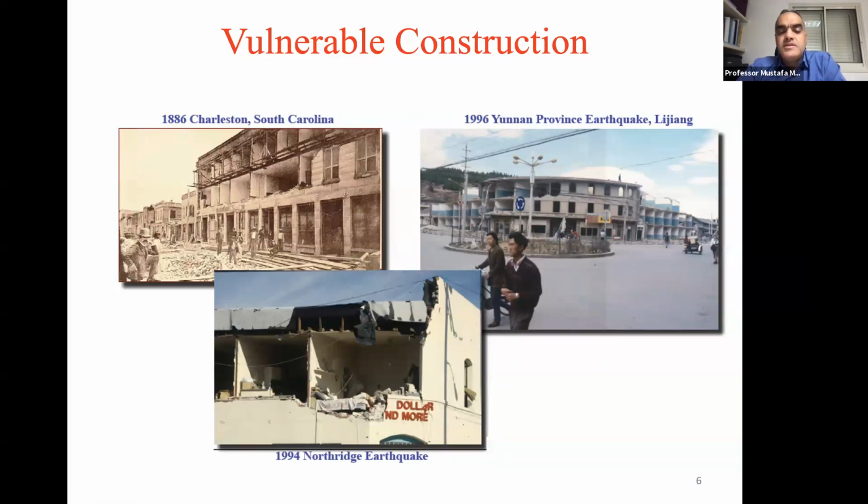So therefore, as a material, it's a brittle material, so it does not have ductility to withstand, for example, earthquake loads. So therefore, during earthquakes, we see a lot of damage or collapse to masonry buildings. So these things have been learned over the years that, of course, we have to make some improvements to make these buildings stand.